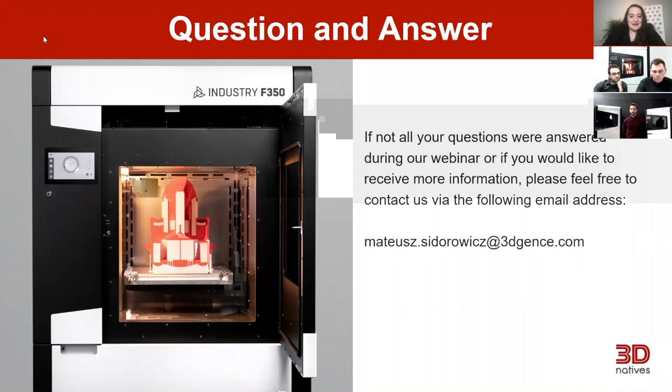Great. Another question from Anna Paula this time. Can thermoplastic polyester be used in FDM printers? Well, the overall answer is yes. I do believe that polyethylene terephthalate, or PET, is chemically a polyester, and it's a fairly commonly used material. So, yeah, the answer is yes, it can be.